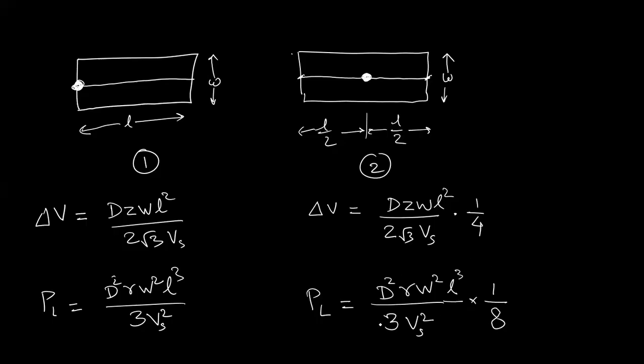So what is this? This is the power loss in the first section. If we take this figure for feeder 1, power loss is this much. And since we have the two feeders which are symmetrical, having the same characteristic, the same power loss will appear in the other feeder also. So we will just multiply that by 2. So this factor is basically 1 by 4. That means power loss is reduced by 4 times in the second case when we place the substation at another location. So that is great, right?